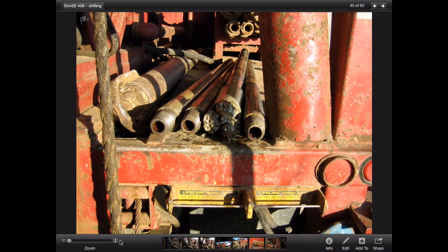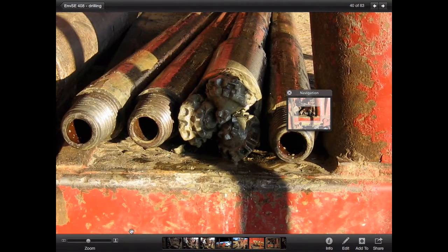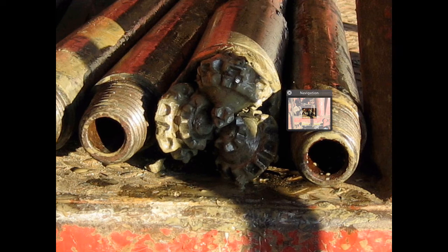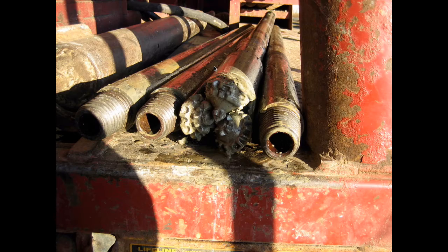This is a tricone bit. Can we make that larger, maybe? So in this case, this is the rotary bit at the bottom. It goes down to the hole and has these cones on it. It's not powered. It just rotates on the bottom, and these button cutters cut off chips, break off chips that get sent to the surface.